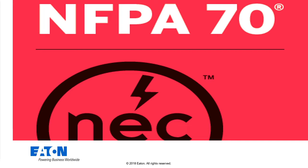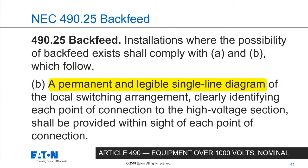Now we'll take a look at the National Electrical Code. So we've been through 70B, and now we're moving into the National Electrical Code. In the NEC, there are just a couple of references that I could find. I think this is the only one I was able to find, where it talks about installations where the possibility of backfeed exists shall comply with A and B, which follow. In B, a permanent and legible single line diagram of the local switching arrangement, clearly identifying each point of connection to the high voltage section, shall be provided within sight of each point of connection.